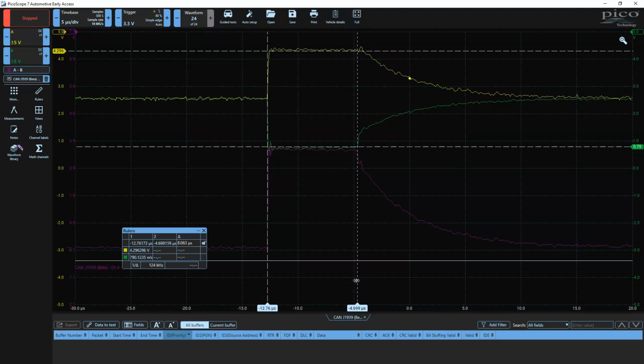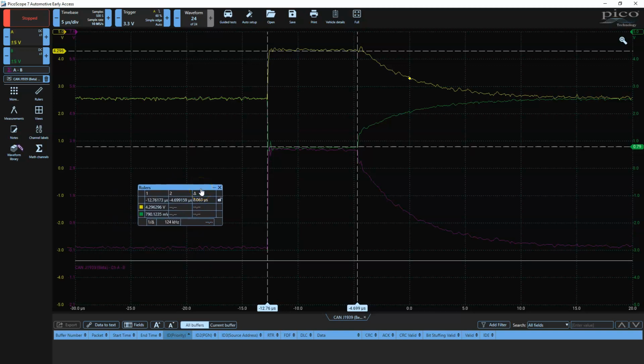So there's that same controller, the engine controller. I don't think there's anything else on the CAN bus that's trying to transmit with that high priority. We can see my 8 microseconds, probably the engine controller. I can't tell what it is because it's given up arbitration. And the reason it gave up arbitration is because of this loss of termination. As I mentioned, going from dominant to recessive is about half a volt. So this won't be considered a recessive bit, even though it's way out here, it becomes a recessive bit.